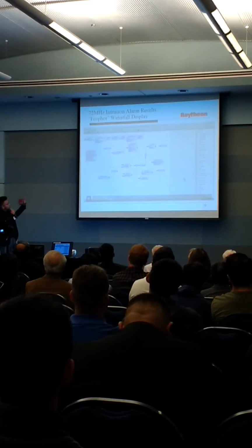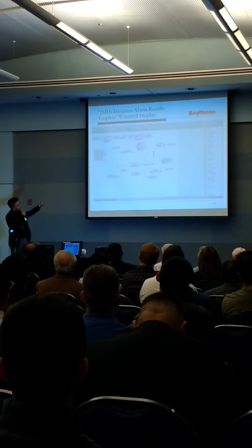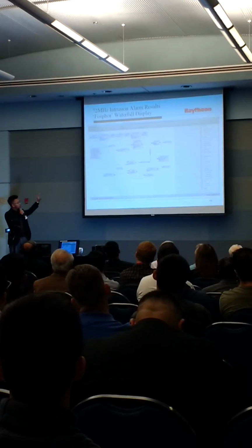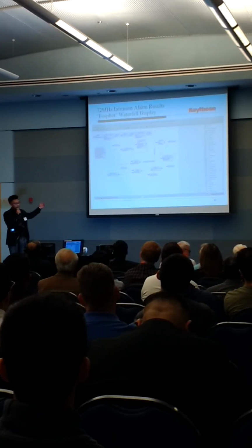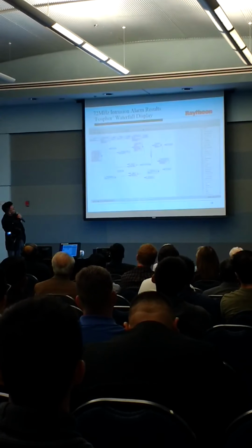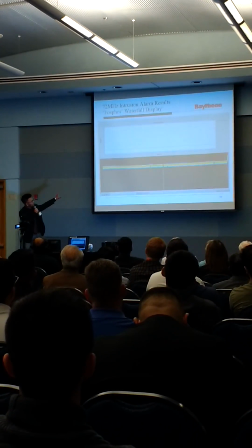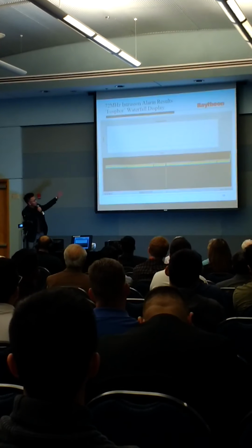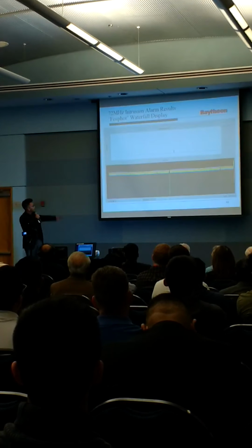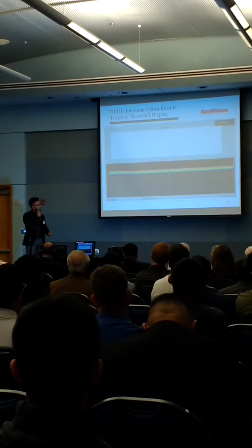So this is our alarm system for the 72 megahertz controller. When we turn it on, we'll see in a bit, it will display a chart on top that indicates 0 or 1. Intrusion has occurred. So here's the chart, and here's the phosphor RTSA and waterfall display. Right now we're tuned to 72 megahertz, and the top chart is indicating a 0, meaning there's no intrusion signal detected.